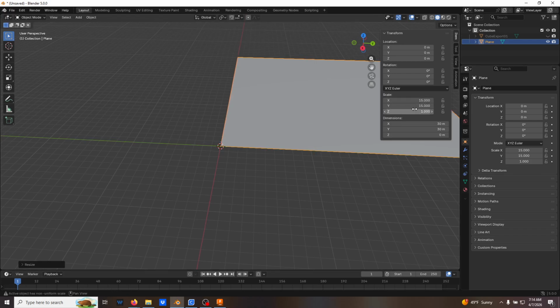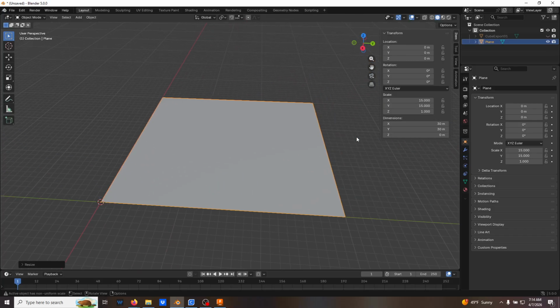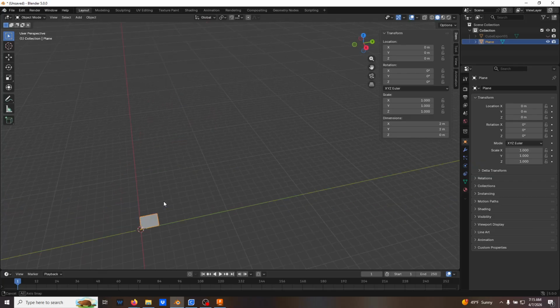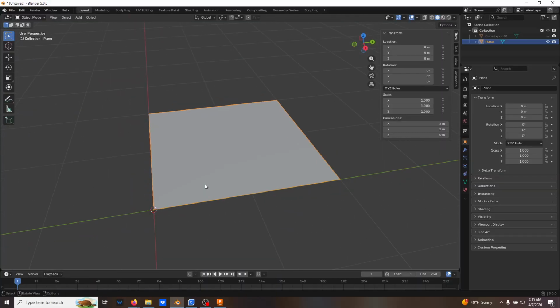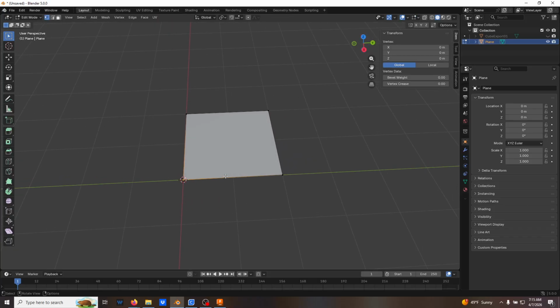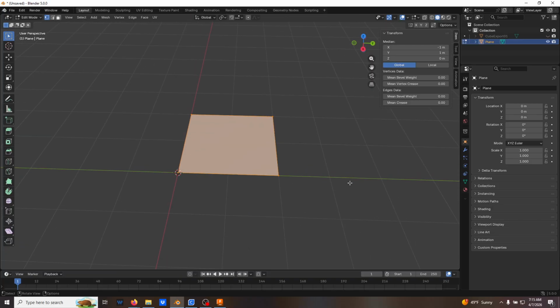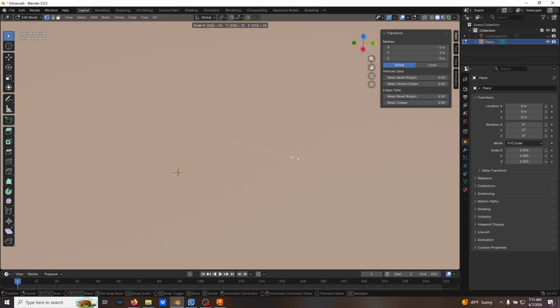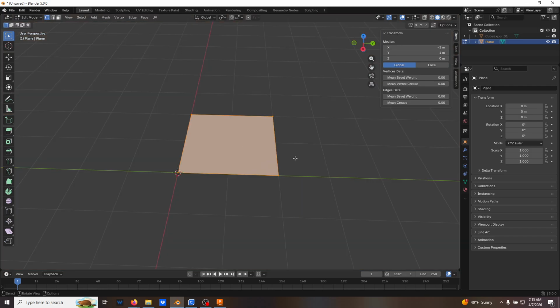Now, one of the things that's interesting here is that I'm running into that same scale issue. I could just apply the scale, but I want to do something different here because I'm doing this in object mode. So I'm going to Control Z to undo this. Now I'll Shift C again to zoom on it. This time I'm going to press Tab and go into edit mode. Then I'll select all these points, and do the same thing: I'm going to scale and press 15. All right. Now, whoops, back up. Screwed that up. Let's zoom out a little bit.